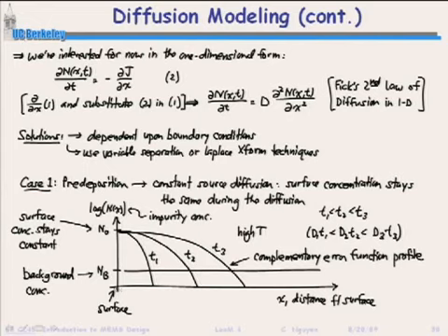And as we go to other times, t2, t3, this moves out, and the concentration at the surface still stays the same because you're continually supplying that. That's what I mean by constant source diffusion. We're supplying the source of dopants at all times. It turns out that when you solve this equation, you end up with a complementary error function profile that's pretty much defined by this equation here, which you can also equate to what's called a complementary error function.